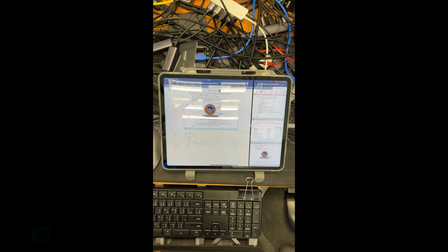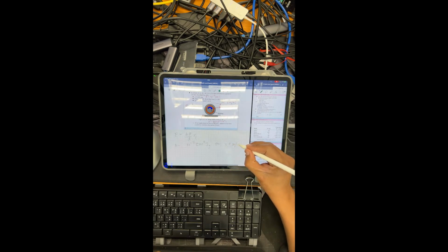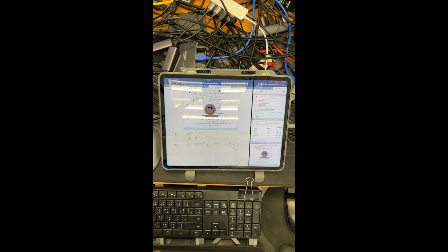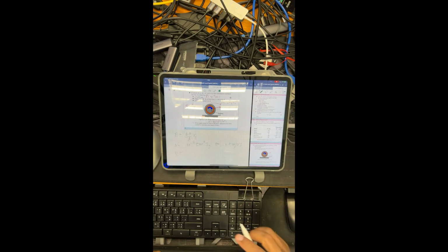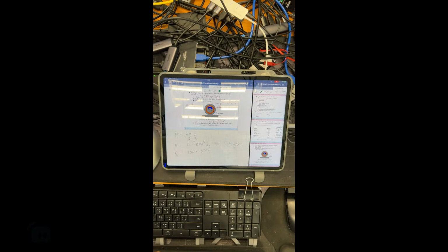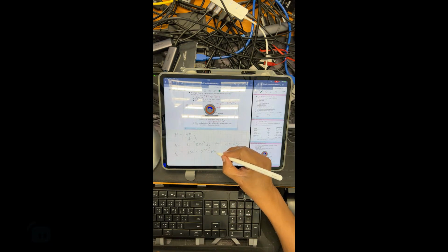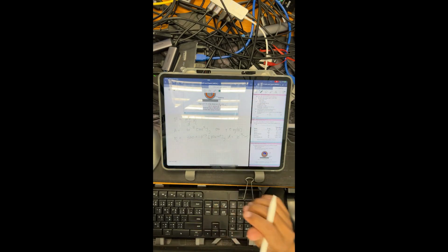And what else? Velocity, the speed, is 1 meter per second. Simply number 1. The next thing is eta, which is what they have provided, 200 millipascal second. So it's 200 times 10 to the negative 3, and the unit in standard form of viscosity is Newton second per square meter. The last one is the distance D, the gap in the yellow area here, which is 1 millimeter, or in the SI system 10 to the negative 3 meter.